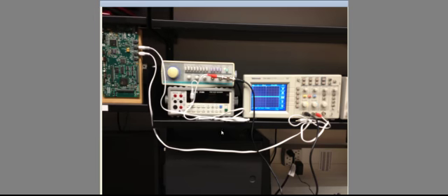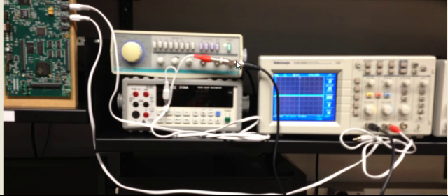You can see the wiring diagram in the picture. The function generator is providing the signal to the line in. So signal is read by the Texas Instrument Board DSK6713, and then it goes through the A to D, and then the filter is going to filter the high frequency signal, and the output is going to the DAC. DAC is connected to this line, which is line out. Line out is going to the channel 2 of the oscilloscope.